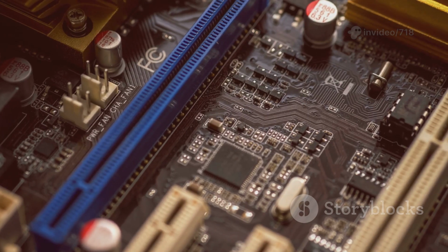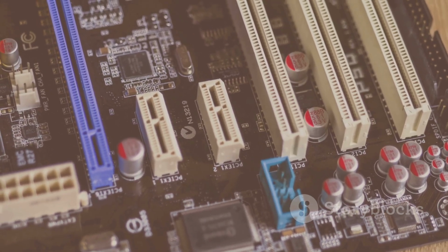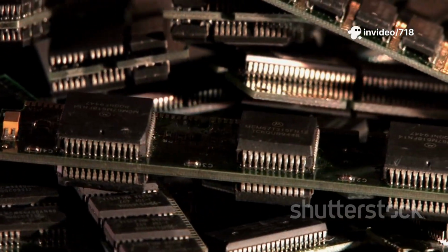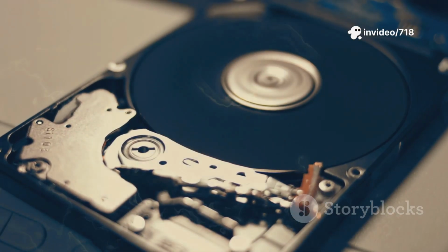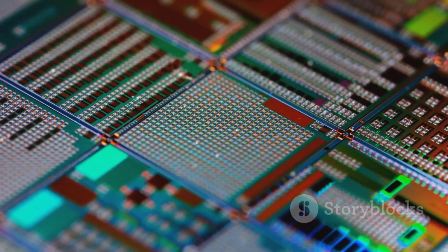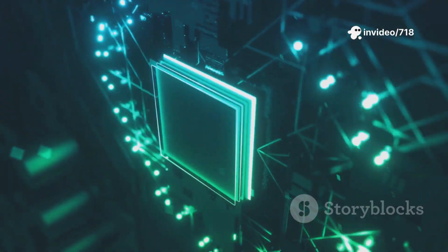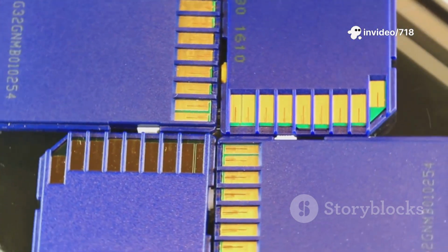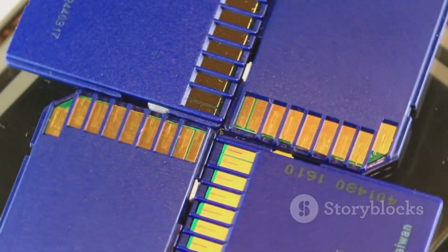When the processor needs to read or write a piece of data, it doesn't just shout into the void, it calls out a specific row and column address. This is the random access part of the name. The processor can jump to any cell at any address in any order with equal speed. To access a specific bit, the memory controller first activates an entire row known as a word line. Think of this as lighting up an entire street in our city grid. This action connects all the capacitors in that row to their corresponding vertical data lines, known as bit lines.